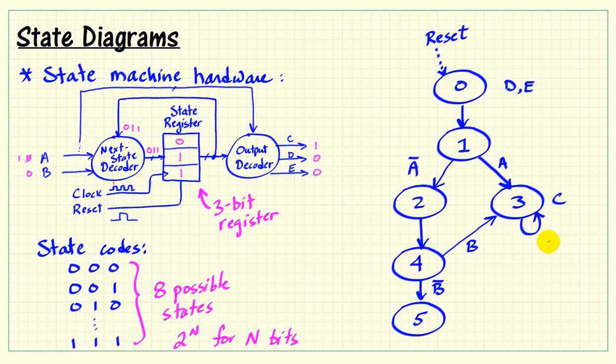Now here's an interesting possibility. Back here in state 3, you don't necessarily have to go to another state. That is, you can use a self loop or a loopback, and this suggests that the way I've drawn this, especially if it's unconditional, that this would also be a type of trap state, because once we're in state 3, we can't get out unless you activate the reset.